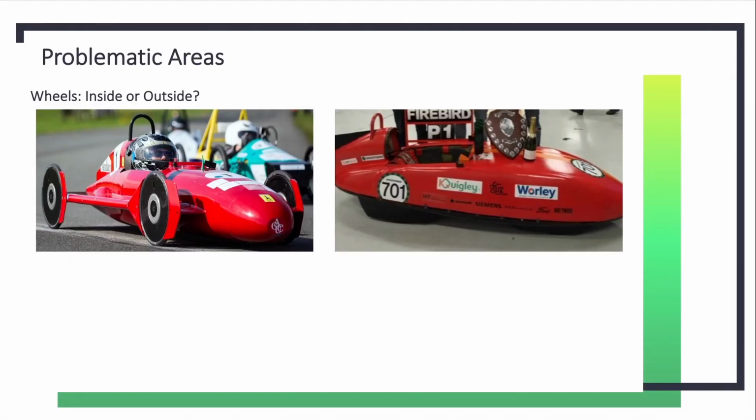In this example here, Dylan has done this by putting fairings on the front. So the airflow hits the fairing, and instead of hitting that front rotating surface, it's now encouraged to go around the side like that and remain attached to the wheel. Similarly, it directs the airflow up and over the top.